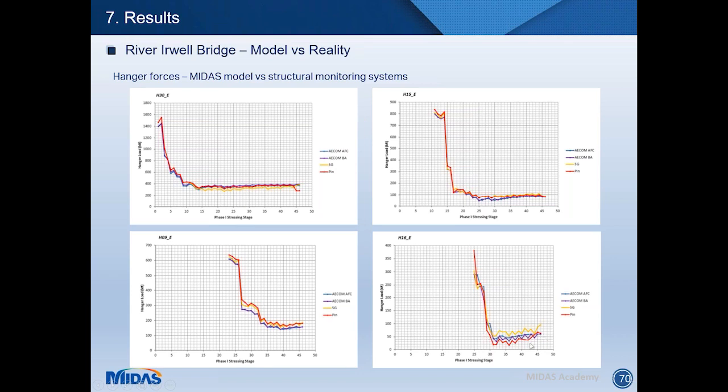So this was of great comfort for us as checker. The designer was getting similar results. These were being communicated between us, and we were comparing results constantly, almost on the daily, during the erection of the arch and the stressing sequence. And obviously also the construction team on site. So having a finite element model that gives you exactly the displacement, exactly the forces that you're reading on site is a good comfort, and it's the only construction control that we have when we're building long span bridges on site, really. So MIDAS was really useful for this project, and it was really a good software, and I highly recommend using it for your project when you're dealing with cable supported structures.